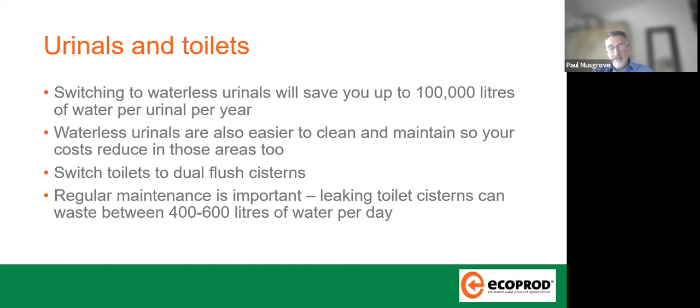However, is it time now to also consider going back to a single flush, maybe possibly around a 4 litre delivery? Because we find that many people are not happy with the dual flush solution, and they end up pressing both the large button and the small button, which kind of defeats the object of why they were actually supplied in the first place. And I think every client should consider their own user group, the abilities of the user group. So hospitals obviously may have people that haven't got the ability to do a dual flush, care homes, etc.